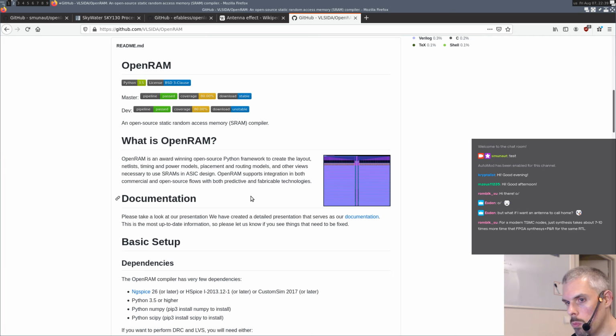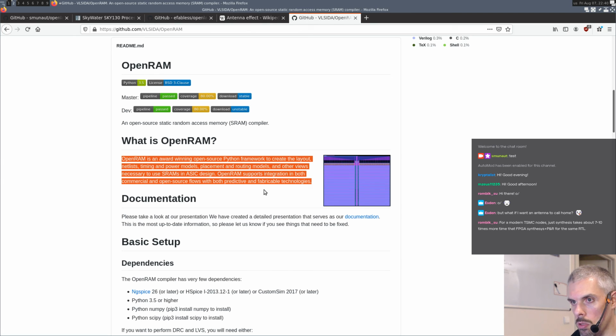And you need one write port to write back the results. And those three ports need to be independent. That's currently not something that's supported in OpenRAM, and that's also something that wouldn't be supported given the SRAM cells that are available for Sky130. They haven't been published yet, but my understanding is that the cells that will be provided by the foundry wouldn't support this kind of three-port configuration.